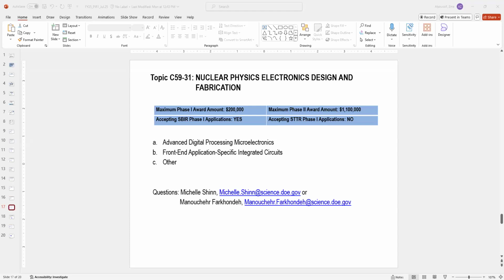Michelle. Okay, so our guest here is asking, what's the expected magnetic flux density at the location of the superconducting front-end ASIC? Well, we know that the SNSPDs are going to sit at around 1.5 Tesla, and we know they can handle it. We have to be rather careful because, of course, if you raise the magnetic field too high, you quit superconducting. So I don't have exact information. That's not in the topic, so you'll need to email me on that.